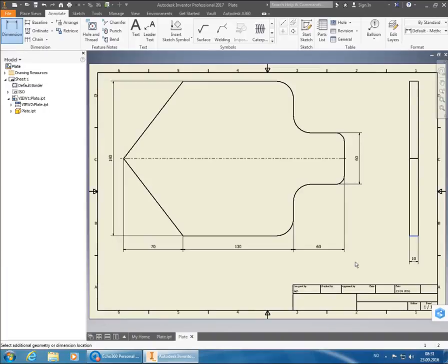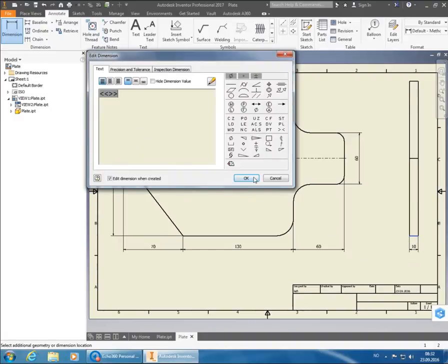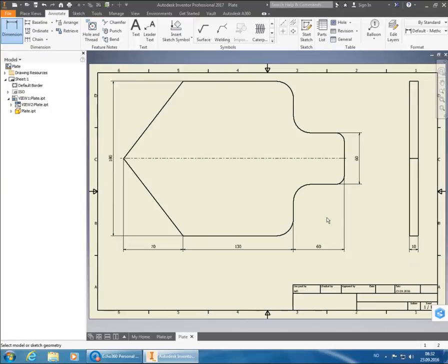Even though I have free space between them here, I can still get it on the same line by holding my mouse pointer over here, getting the yellow dot, and then moving it carefully over here. And already at this point, I can place my dimension there. So I can click my mouse button, then it's set in place. And if you put a ruler on the sheet of paper once you've printed it, you'll see that everything here is on one line.